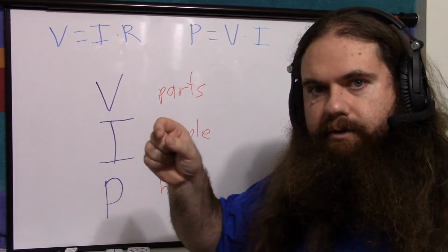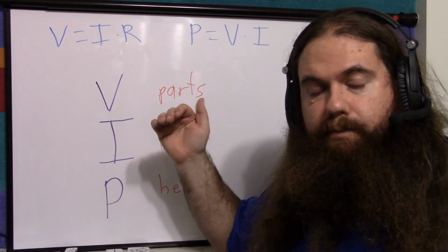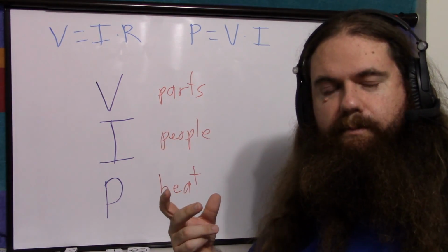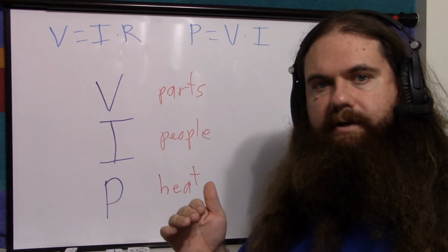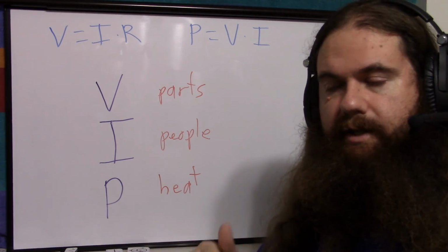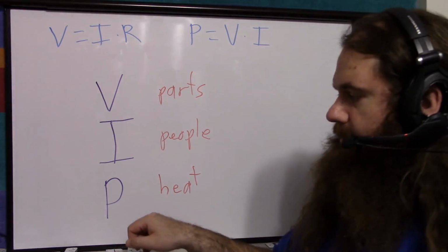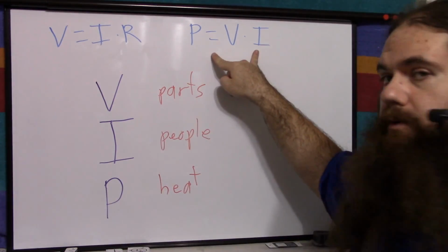And we can just turn it down by adding resistors in parallel with the oscilloscope probe. For example, take a 10 mega ohm oscilloscope probe. Add a 10 mega ohm resistor in parallel with it. Now it's effectively a 5 mega ohm resistance. For example, we can bring it down gently that way. And heat, for an oscilloscope, is no problem because we're already limiting both voltage and current. Oh, look, we're limiting power.